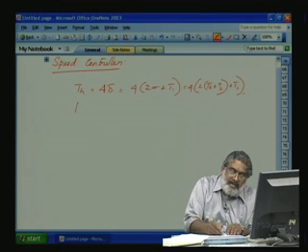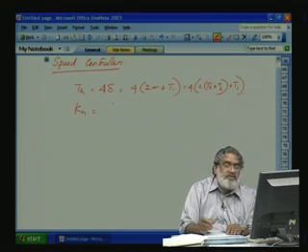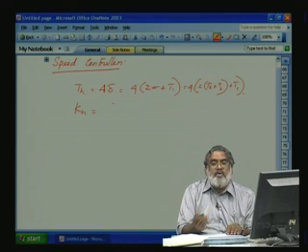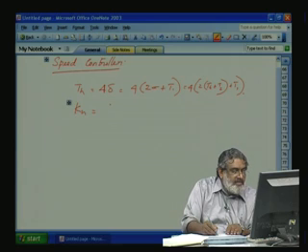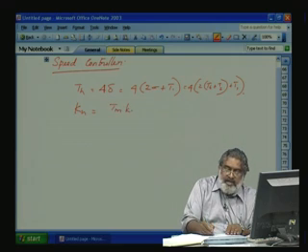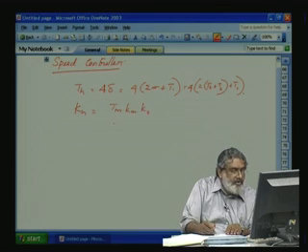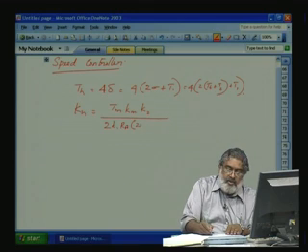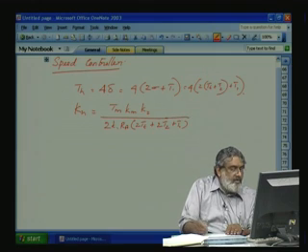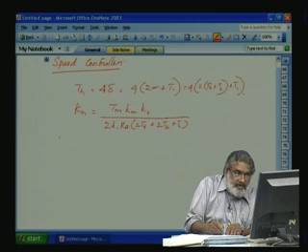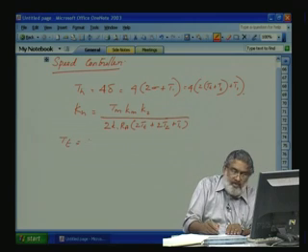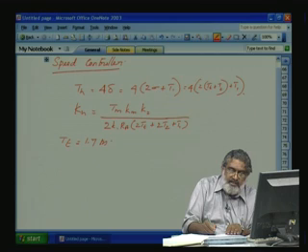from the converter, and the speed feedback filter time constant. Okay, Tn, and Kn is equal to, so we can use either symmetric optimization through equations or graphical method. So let us take this one from the equation method. This will be equal to Tm Km. This is the machine constant, K2 divided by 2 K1 Ra into Tt plus 2 T2 plus T1. See, we have to substitute this equation and we have to find out only. So Tt we know it. So we will derive Tt is equal to 1.7 millisecond.